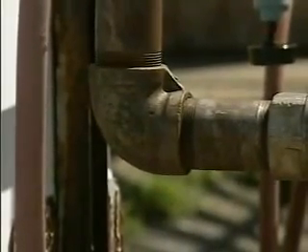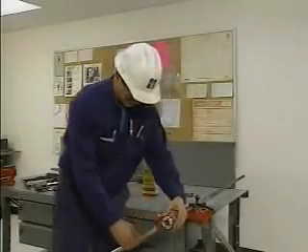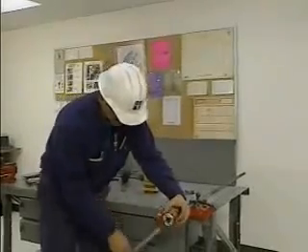A variety of sizes and types of individual pipes can be connected by joints and fittings to form a larger piping system. Before the pipe can be installed, the length of the pipe that you need must be determined. The pipe must be cut to size, and the pipe must be threaded. In this part, we'll see how to use a pipe die to cut threads on a pipe. The threads of a pipe are created with a pipe die.